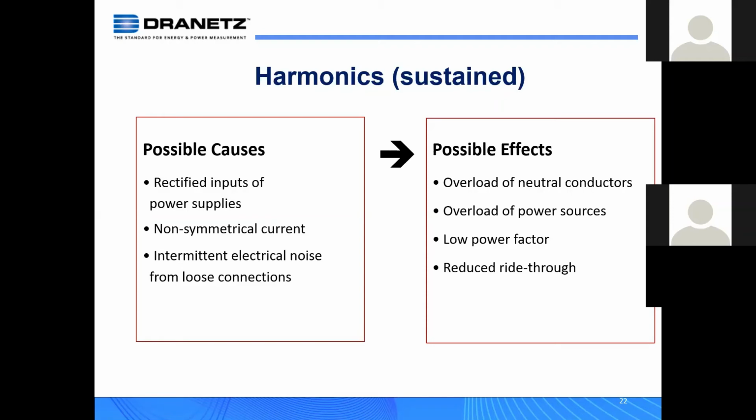Motors are very interesting because motors are susceptible to harmonic problems. But also when you measure harmonics at the terminals of a motor, like a VFD or something like that, if there's a problem with the motor, a rotor problem, a stator problem, or something like that, that is also reflected onto the system. And motor signature analyzers, very specialized instruments, can detect that and say, well, with this signature, you have a rotor problem or whatever. So they're unique in that they can be affected negatively by harmonics, but also cause harmonics that we can use as diagnostic information to see if something's not operating properly with them. So it's part of the maintenance of motors, I guess, is the point.